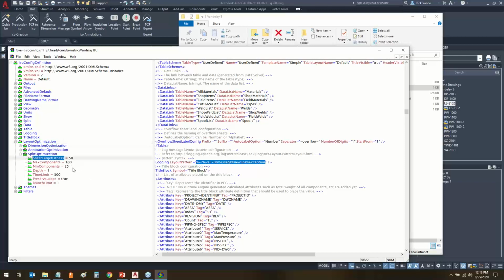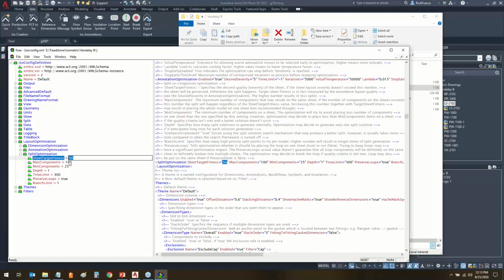I was playing here one time and I doubled this number and doubled this number just to see what would happen. ISO that normally took 45 seconds to create suddenly was taking 30 minutes to create. So just tweaking the wrong thing here, you can wreak havoc on how it's creating stuff. So my opinion there, all that's set in there, just leave this as is.